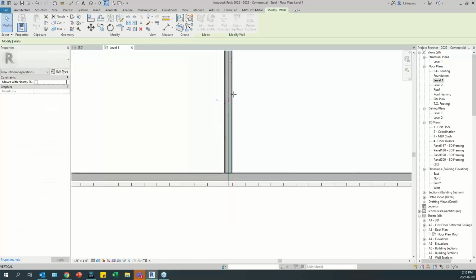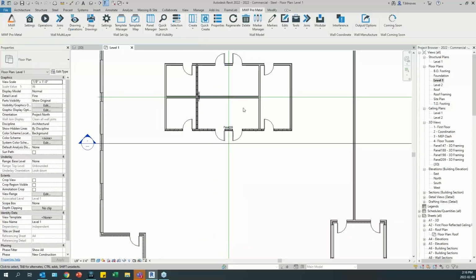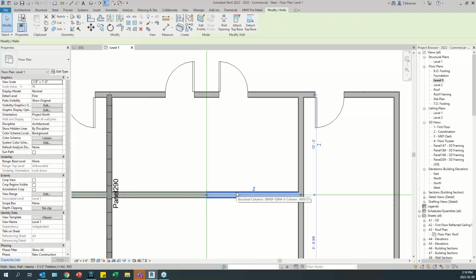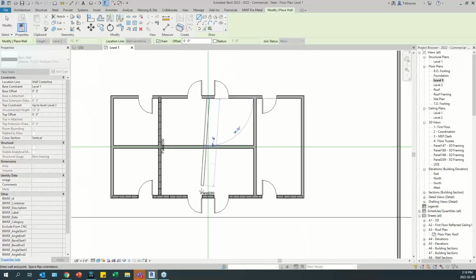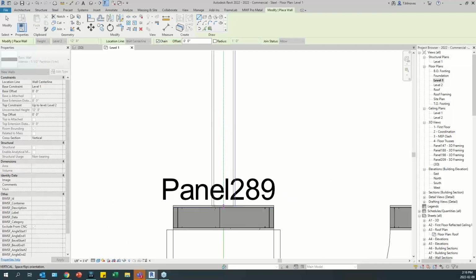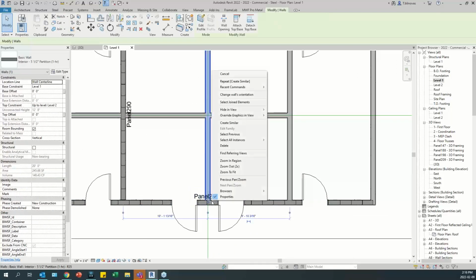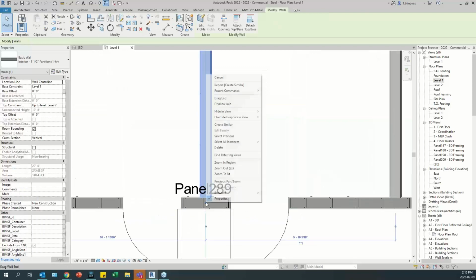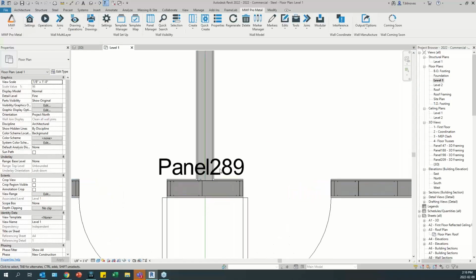We're going to just drag this back, or you could just hit delete here and create another wall again. So let's say we're going to create one here. So this portion would be joined, okay? And we can just create a rule here for this T intersection.